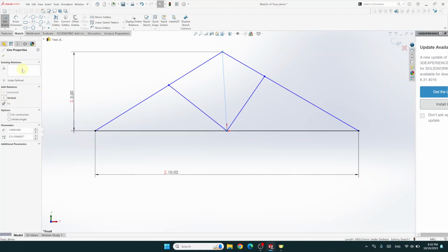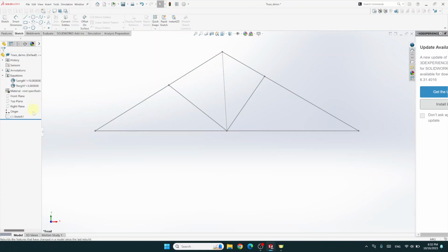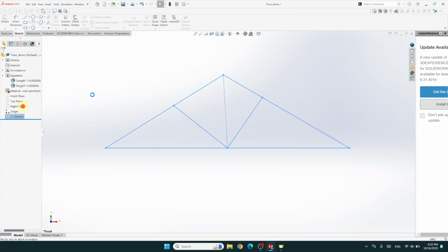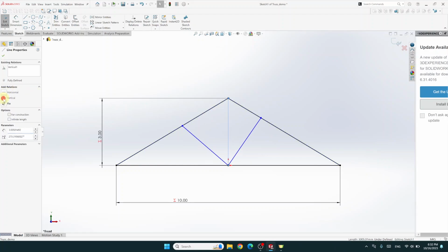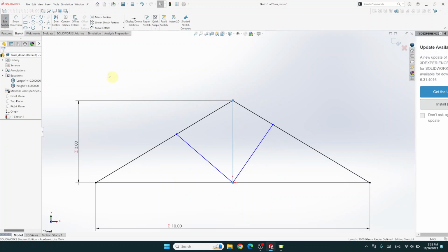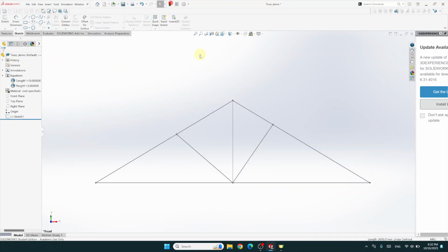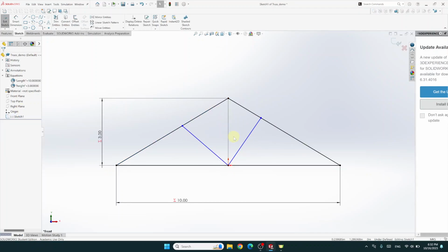Okay. It didn't like it. What happened? Let's try it again. Let's make a refresh and edit my sketch. Click on that line and click on vertical. Here we go. It comes. Yeah. Sometimes you just need to click the little light, traffic light, and it helps. And you click on enter. So now it's vertical. Let's click on the little lights just to make sure.